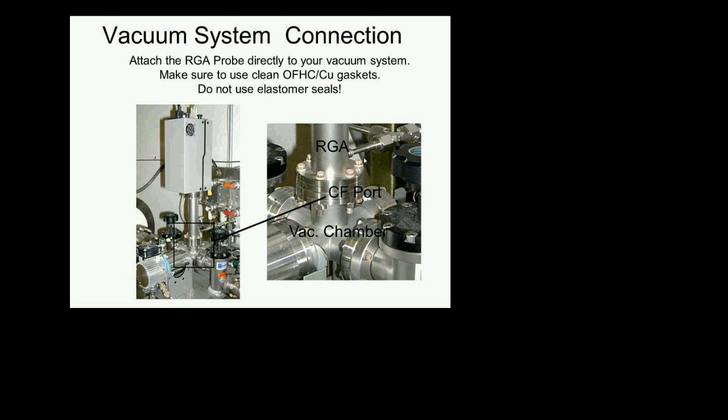So yeah, it doesn't really matter what material you use. Of course, if you can't use copper, because it's going to contaminate your process, whether it's semiconductor or whatever, then don't use it. Silver plating is fine. Aluminum gaskets are fine. So, for example, if you absolutely have to use Klein flanges, or quick connect flanges, then don't use rubber O-rings, but rather use aluminum gaskets.